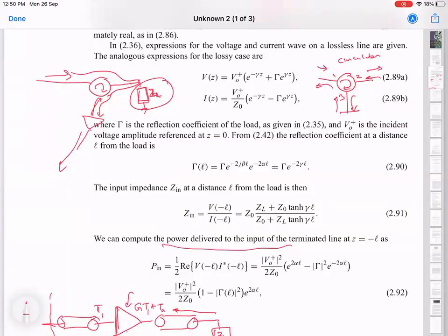If for some reason you're not able to use an impedance transformer, in order to minimize reflections and standing waves, you can actually put a small amount of attenuation in the system. It's basically like saying if you have a section of transmission line which has some reflection on both ends, the standing waves will get reduced if the line is lossy, just because the signal is propagating back and forth and its signals are actually dying down. So that can sometimes give you a crude way of reducing reflections in a real setup.